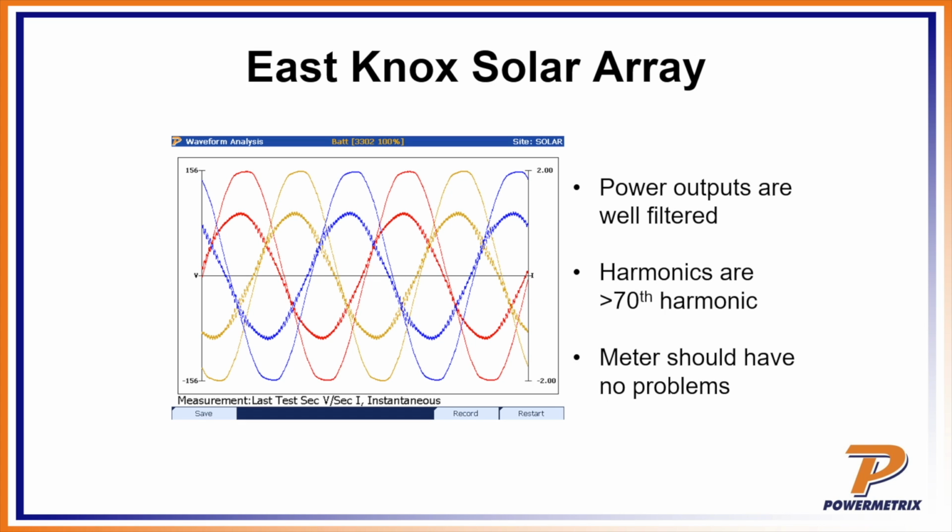Harmonic energy is typically not your friend in the sense that it's not, once again, doing useful work. Most harmonic energy is being given up as heat. And so for the utility, that's not a good thing because hot equipment wears out faster than equipment that's not hot. And so harmonics, if it's generating lots of heat, means that over time, you're going to see more maintenance costs going into replacing transformers, meters, other equipment as it runs hot because of those harmonics. And so it really behooves the utility and ultimately the customer to try and reduce that harmonic energy as much as possible.